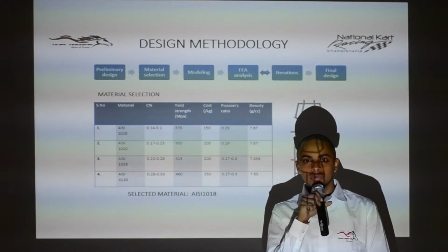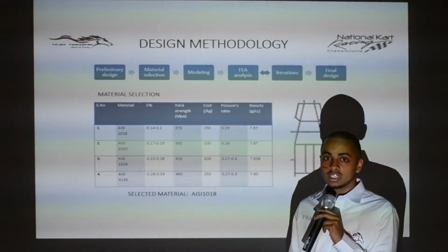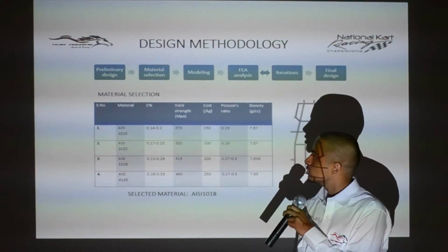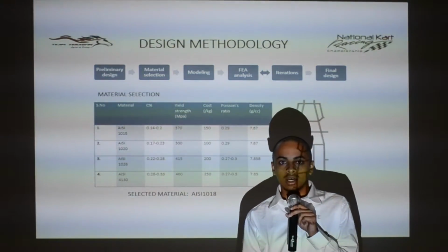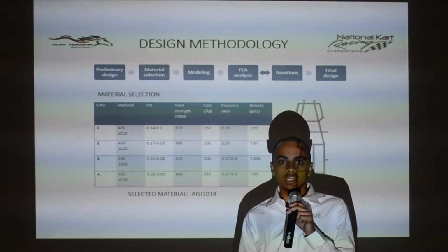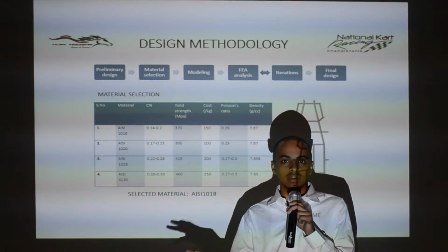Hello, I am Mr. Mani Bandari from Team Terasvin, and I will be guiding you through the next 33 slides. So, the design methodology that we use in our go-kart is as follows. For the preliminary design, to get the basic idea about how to design our go-kart, we made a prototype using PVC pipes and we fixed the wheelbase and the track width for our go-kart.